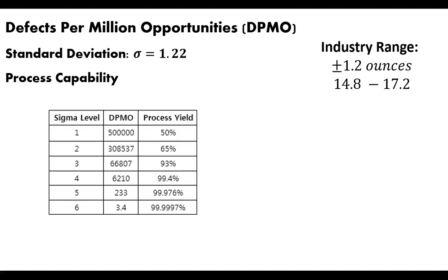And if we consider, again, this standard deviation, and with this as our specification limits, where we want to operate within, what we are finding is that we're operating at 2 standard deviations based on this limit and the specification. So that's 2 standard deviations out. And what we're finding is that we're only giving our customer what they want 2/3 of the time, which makes sense. That's exactly what we found on the last slide.